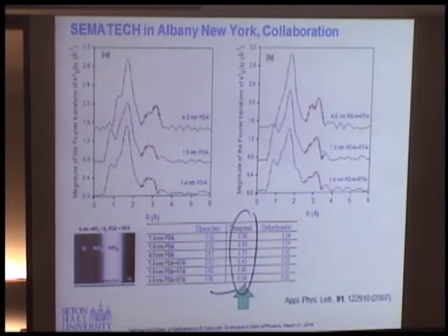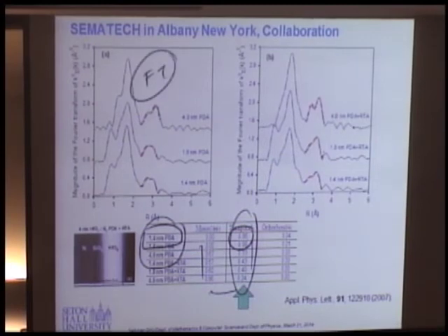So when the tetragonal is low, it's all monoclinic. Then as the tetragonal goes up, monoclinic goes down. And these are the PDA and the thickness of the film, 1.4 nanometer, 1.8 nanometer, 1.4 nanometer films. And we figured out if you use these 2 conditions, you get almost 96 to 99% of the tetragonal phase, which the industry wants. Okay? That was the thing. They don't want monoclinic phase, they want the tetragonal phase. How do we know? This is our Fourier transform data from Brookhaven, and from the analysis of this 1.8 and 1.4, we know that this structure is tetragonal.